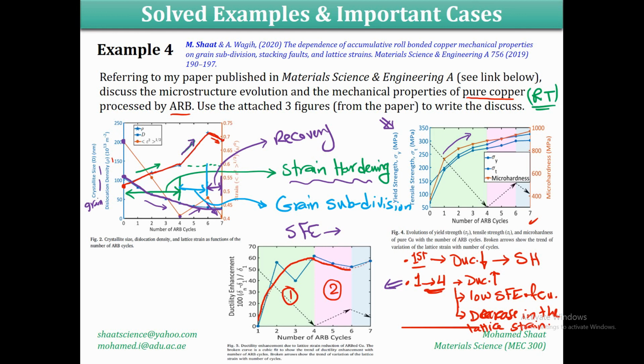The main reason behind it is more overlapping has been generated between the dislocations, which resulted in an increase in the lattice strain and more impedance for the grains to glide or to move or to rotate inside the material microstructure, indicating a decrease in the ductility.